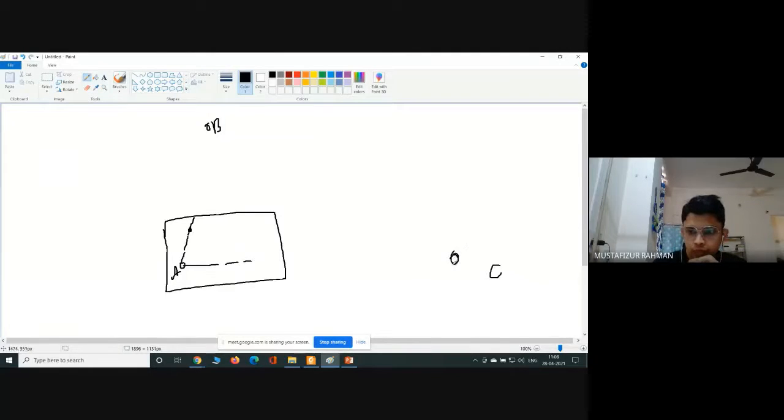Now at this point we can go. So we know, okay, this is C point here. We can measure the direction. We can know the direction by looking here and through the alidade, marking the direction and measuring the distance and putting it in a proper scale. So we know A point, we know C point.